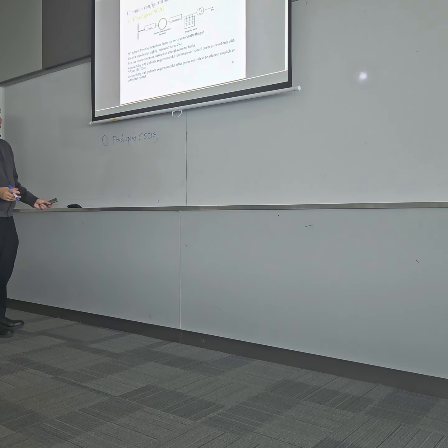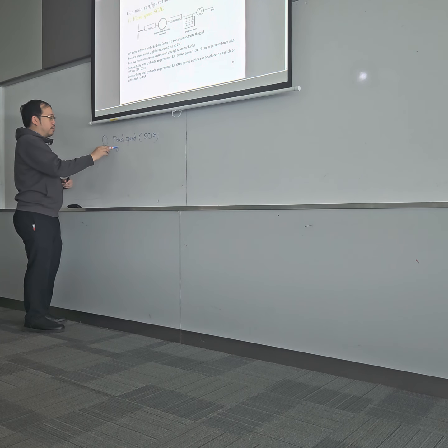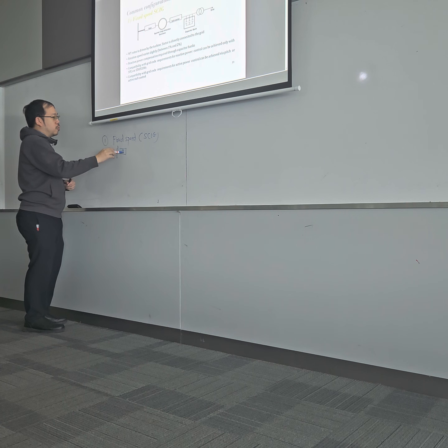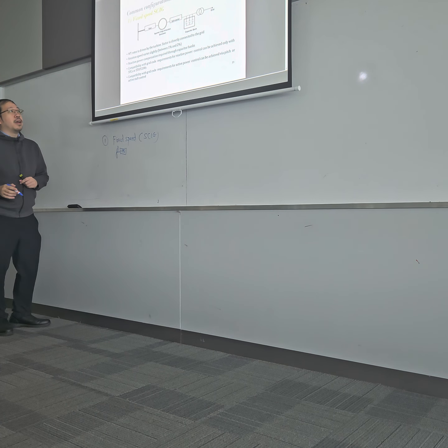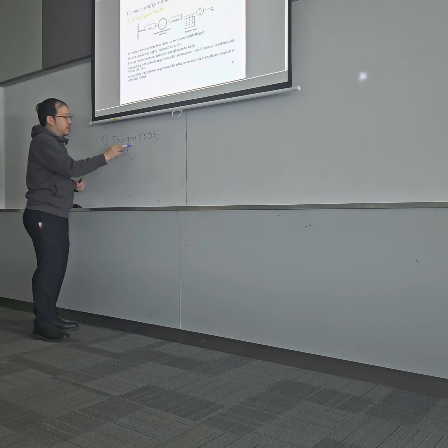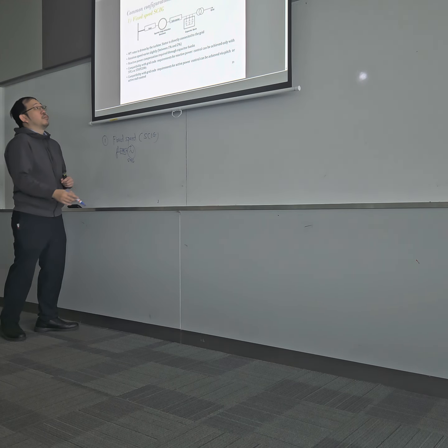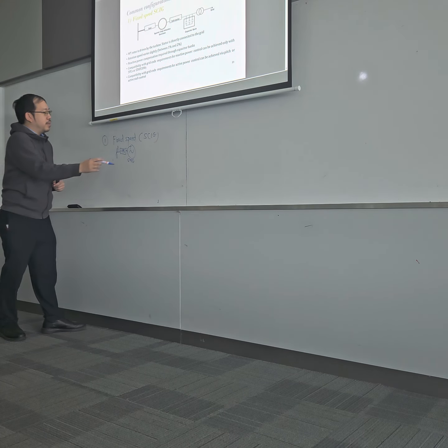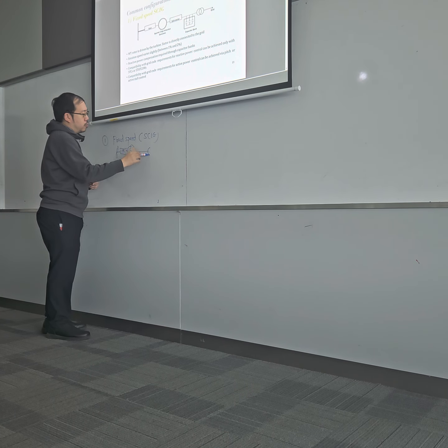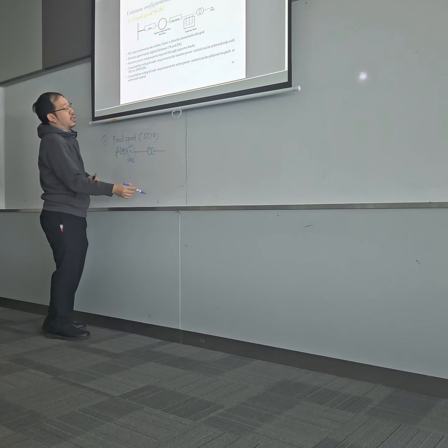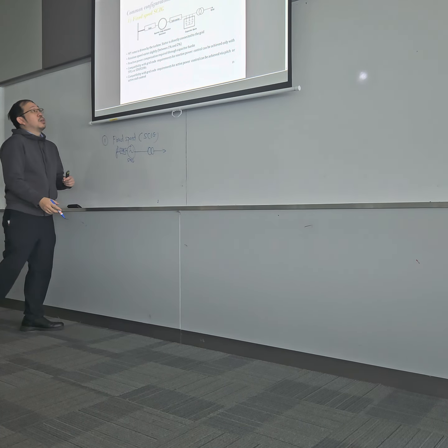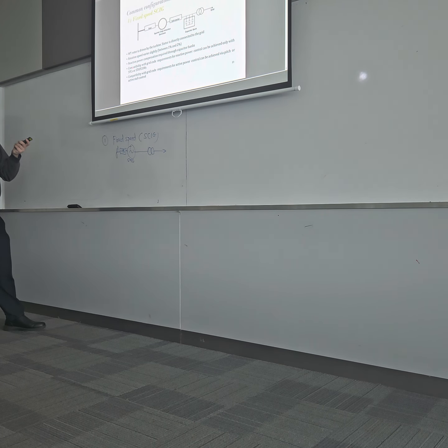If you were to draw it, basically you have your wind turbine followed by the gearbox, and the generator, followed by transformers and so on. Okay, so this is driven by the turbine and your stator is directly connected to the grid.